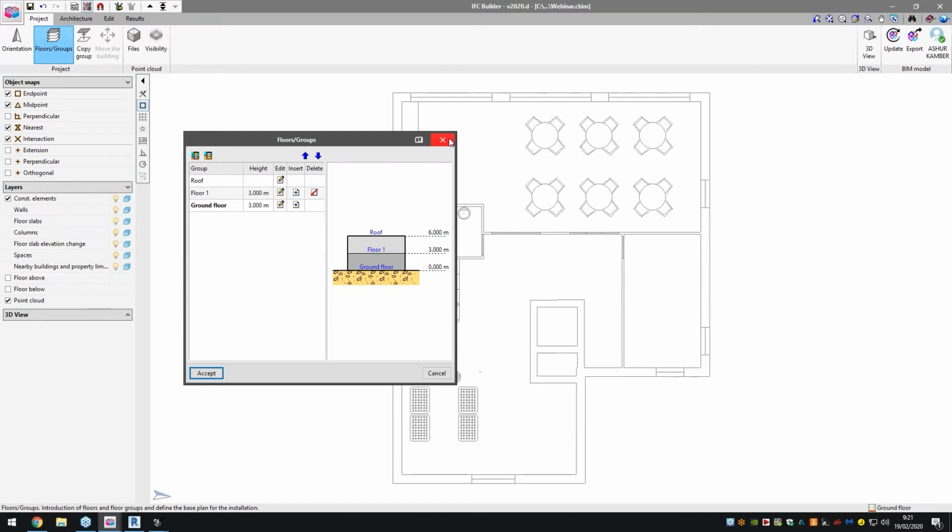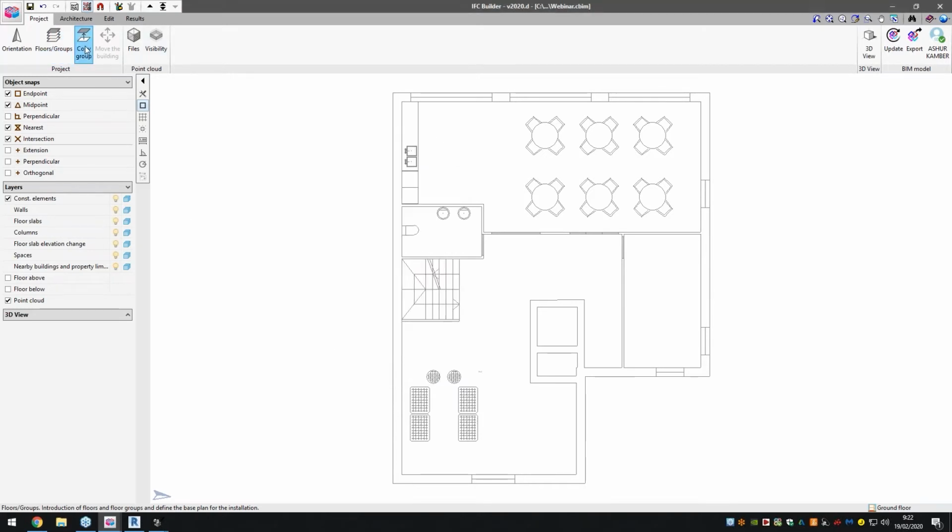Sufak asks, now it's a specific question, whether we can make different heights in the same floor, like a part of the floor is 5 meters high and the other is 4 meters. What you need to do, just in short, is create 2 separate floors and define them as such as well, so the program understands that. But of course, I'll go into more detail about it a bit later if that doesn't answer your question. But moving on.